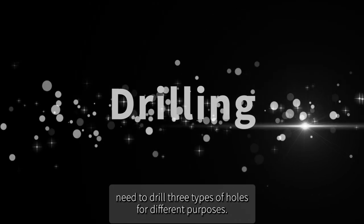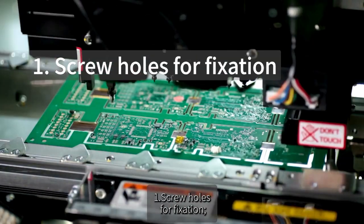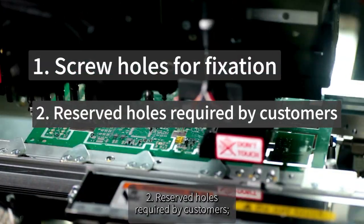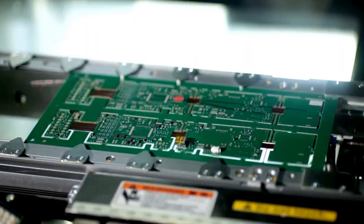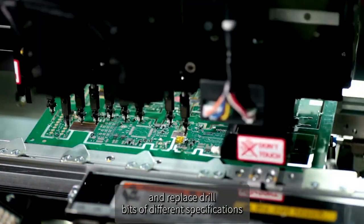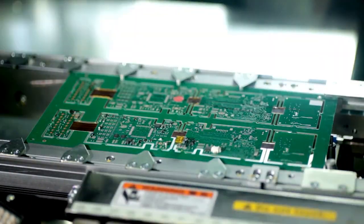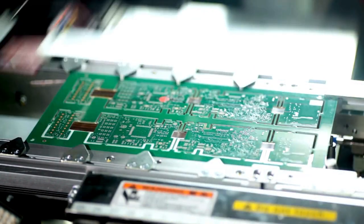Drilling. PCB boards need to drill three types of holes for different purposes. 1. Screw holes for fixation. 2. Reserved holes required by customers. 3. Via hole for user line conduction. The automatic drilling machine will automatically select and replace drill bits of different specifications according to requirements for drilling operations. The smallest drill bit can reach 0.2 mm.